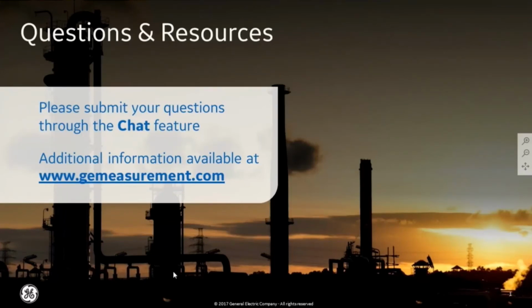Okay. And then a question about during the TCG calibration, why is there no TCG curve on the A scan? The short answer is that feature has not yet been implemented in the instrument. Again, coming in 2.0, especially on the conventional channel side, there's been a lot of work done around amplitude evaluation techniques. DAC and TCG are going to be available there. They are displayed on the A scan during work.